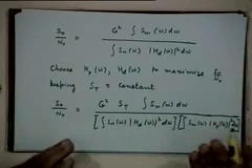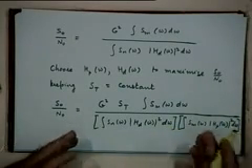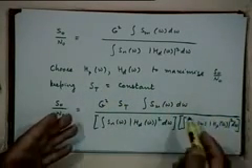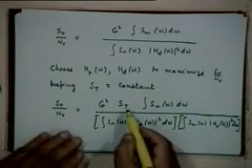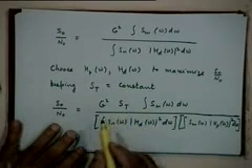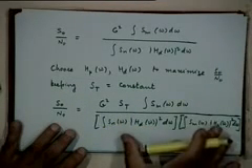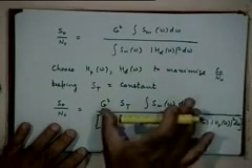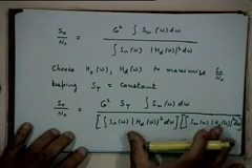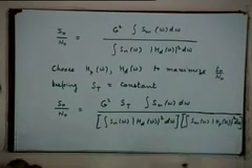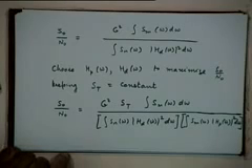Sm omega is a property of the signal, right. So there is not much to it. It does not depend on Hp omega, Ht omega at all, because you are keeping St anyway constant, right, in that sense. So therefore what we can do is we can maximize this quantity by minimizing the denominator, right, in some sense. But let me not jump to any conclusions, we will just see what that means.